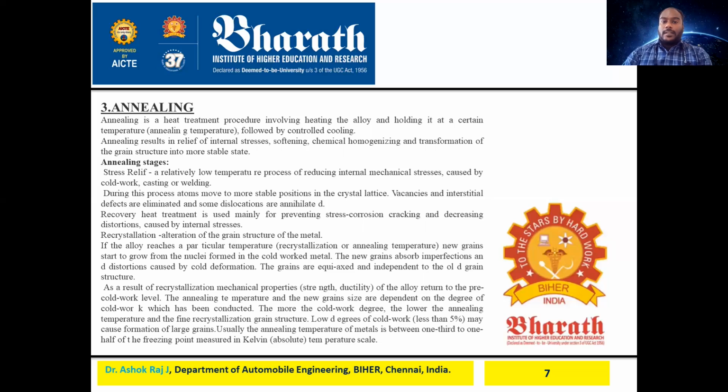What are the annealing stages? First is stress relief, a relatively low temperature process of reducing internal mechanical stress caused by cold working or welding or casting. During this process, atoms move to more stable positions in the crystal structure, and vacancies and interstitial defects are eliminated and some dislocations are also annulled.